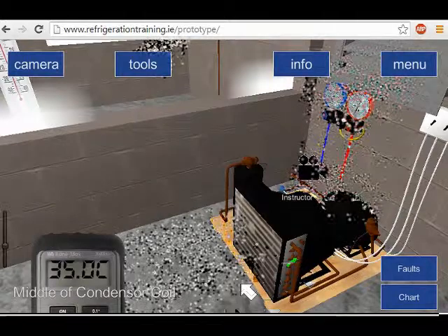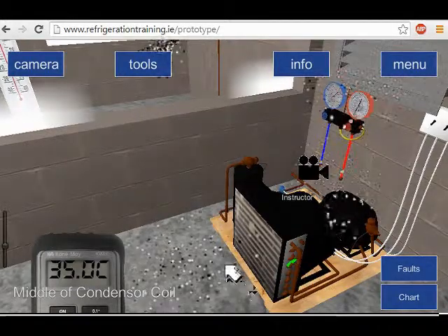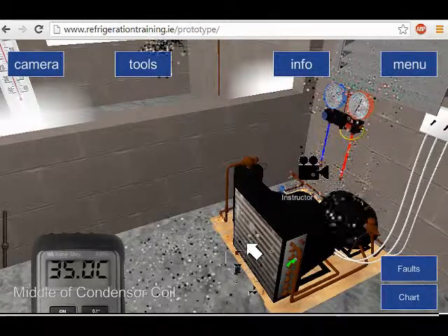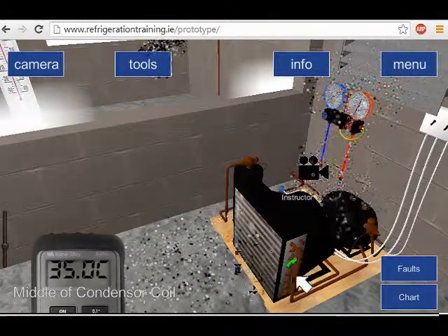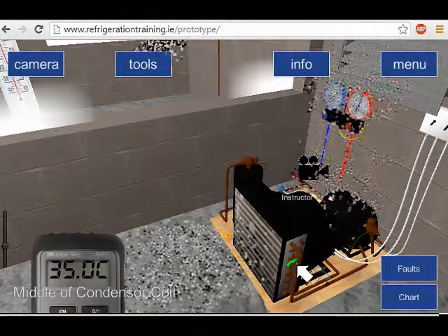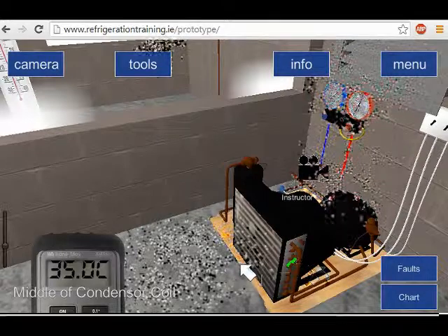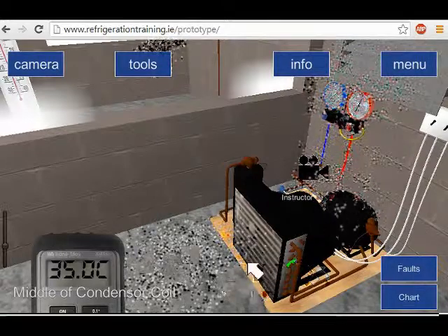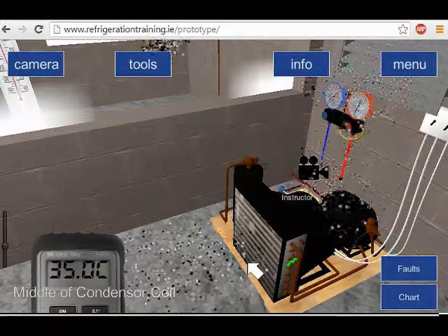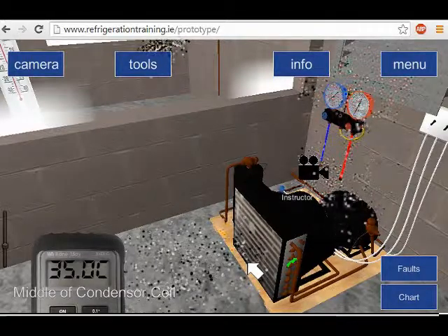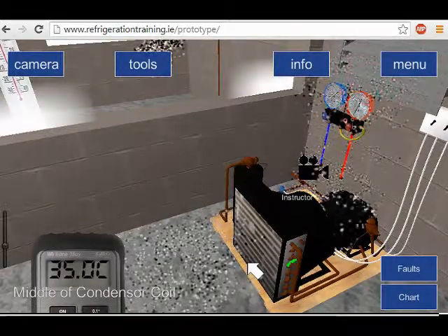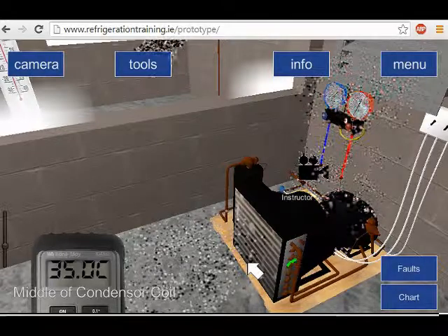Now, if you wanted to show off and have a little bit more wording, you could turn around and say, should the air on increase from 20 to 25 or to 30 degrees, then you would expect your condensing temperature with a 15 degree delta T total here. So if I increase it to 30 degrees and add 15, I would expect my condensing temperature to be up at 45 degrees Celsius. That makes sense? So that's what assignment 3 is about, showing that you understand that 35 degrees today could be 45 degrees tomorrow, all right?